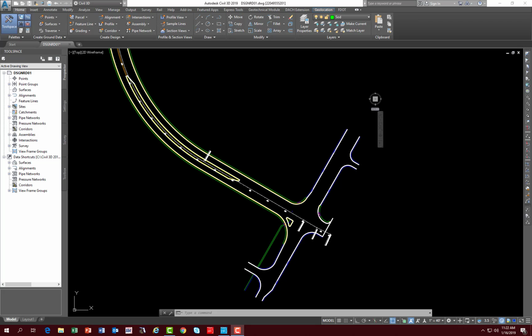The entities that are already placed will either have the pay item data, which is also known as X data, attached, or will need the X data to be attached using EMX. Using the EMX drawing tools, the designer can draw line work with the X data attached and have confidence it is on the correct layer and using the correct line type.